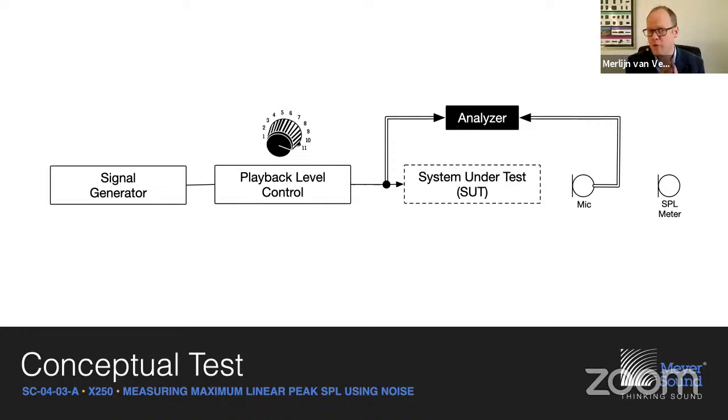And that means that for that microphone, it's perfectly fine to live in the near field of the loudspeaker because we're not trying to get a boutique transfer function. We only want to see a relative change in the shape of the transfer function and its coherence. Whereas the sound level meter that is ultimately used to determine the SPL at a given playback level in the interest of a data sheet or other applications, that microphone needs to live in the far field. And the far field is a moving target, if you will.